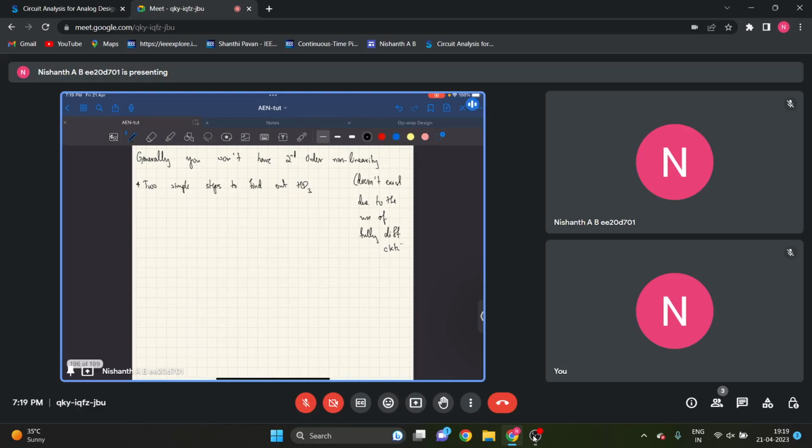Okay, so what does that mean? G2 is 0 in our previous example, and hence to find the linear equation, what should you do? Assume the circuit is linear, provide an input voltage, check what is the output voltage. This is step 1.